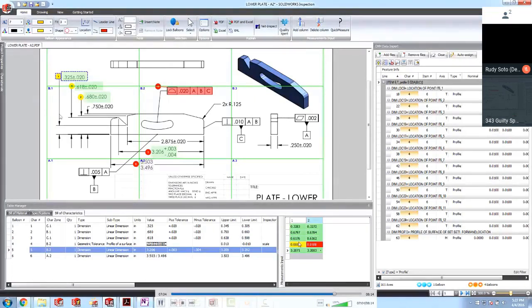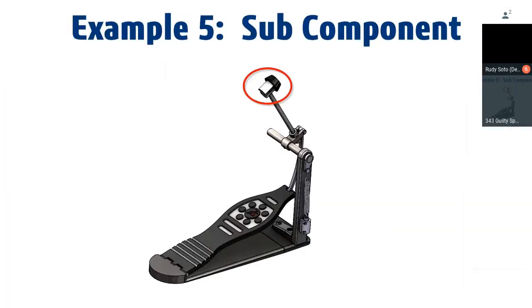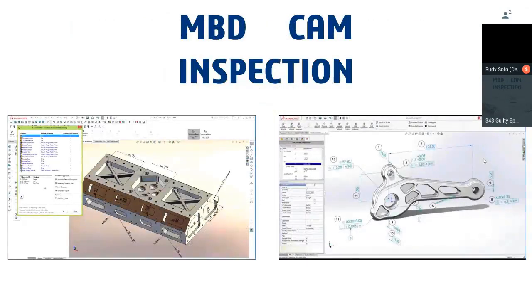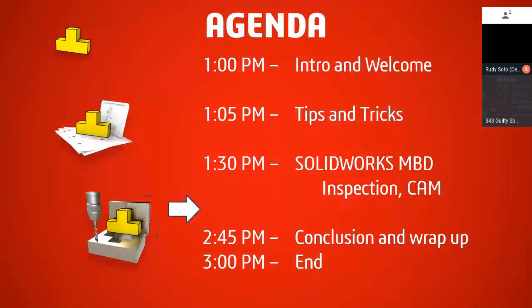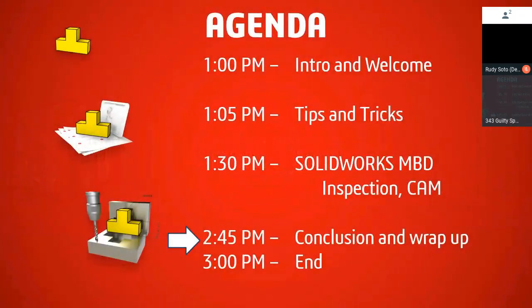And that's the basic gist of SolidWorks MBD, SolidWorks CAM, and SolidWorks Inspection, and how they're all tied together, right? We do what's called PMI, and we utilize that PMI, which is essentially the product manufacturing information. It's the geometry of the model, but also the tolerancing, geometric tolerancing, and surface finish information. It could also be additional things like notes.